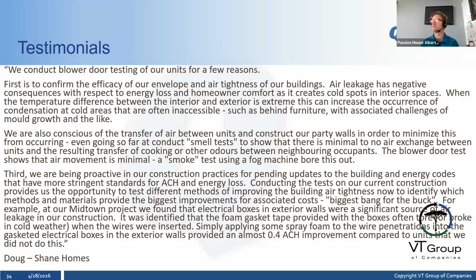that one where I showed where we had it was the all closed cell spray foam assembly in the steel stud house. After I visited that site, he went straight out to Performance House out in Edmonton and bought a box of Sika tape, right? Because we found all these little details that, based on how finishings go, there was no other way to get to the air barrier at this stage. So he had to go out and get a whole bunch of tape. So sometimes that's the conversation we have.